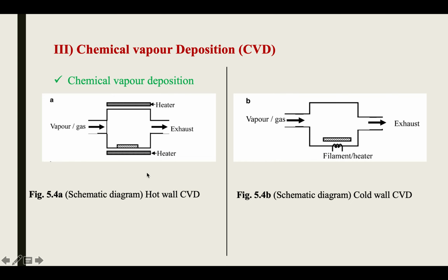In a hot wall setup, the deposition can take place even on the reactor wall. This is avoided in the cold wall design, where the reactant will not get deposited on the cold wall. So this is the plus point for the cold wall design. Besides this, the reaction can take place in the gas phase with hot wall design, which is suppressed in cold wall setup. Further, coupling of plasma with chemical reaction is feasible in cold wall setup.